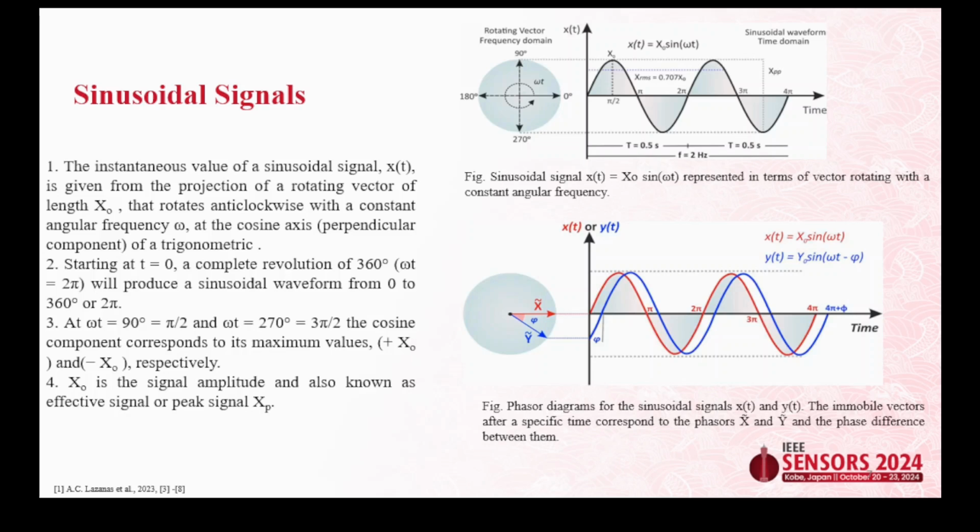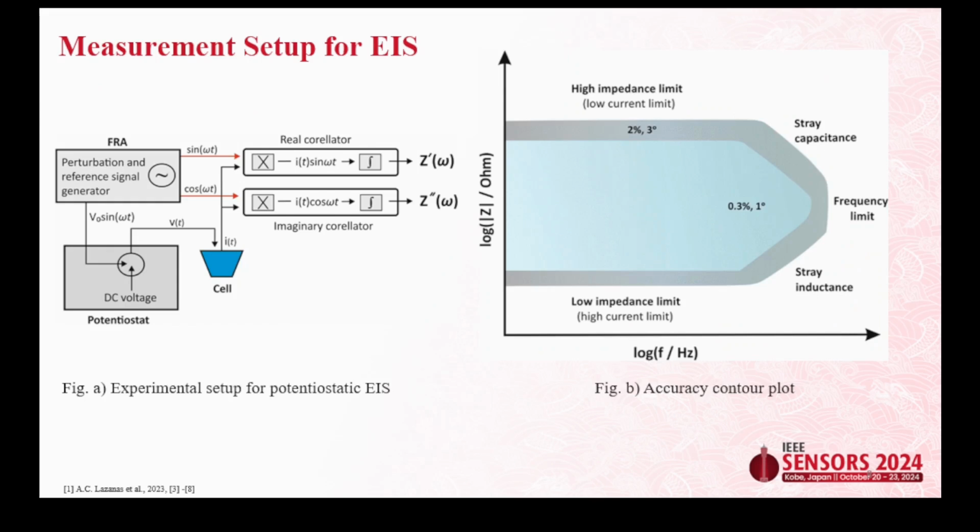So while taking the measurement, if it's a resistive element and there is no capacitor or inductor parameter involved, then in that case the amplitude change will actually give us an indication about the response of the device. But if there is a capacitor or an inductor value involved, then in that case there will be a lagging of signal. The current and the voltage will lag behind each other based upon whether there is a capacitive or an inductive element involved in the process.